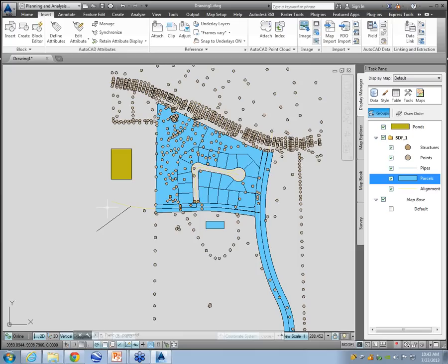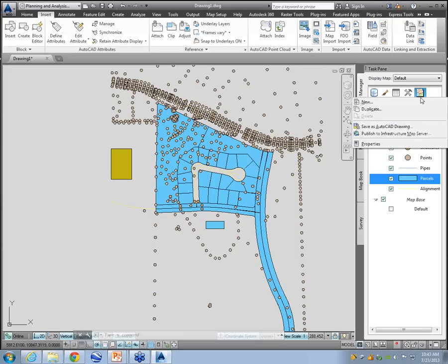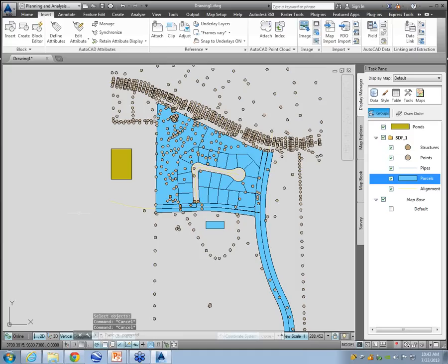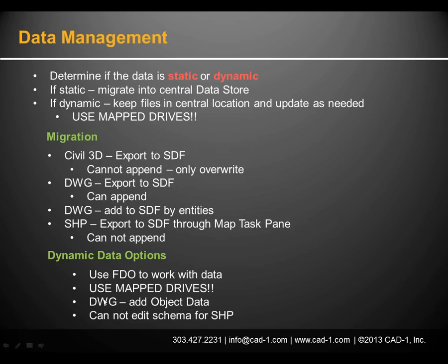But here's something better. Let me erase that. I can give this drawing to somebody with AutoCAD, and they'll see every bit and piece of it if I just use this tool right here. So in my Map tool, I want to say save my map as an AutoCAD drawing. It's going to just take a picture of everything in here, save it as AutoCAD objects, and somebody with LT or plain AutoCAD can see this and work with it all day long. They don't get to see any of my attribute information, any of my cool data, but they didn't get to see my object data a minute ago. So I'm not crazy about that option. I'm not crazy about the people who say, oh, I just want to work with AutoCAD drawings, and can't I make them intelligent? Well, yeah, you can, but still, you're crippling your drawing.